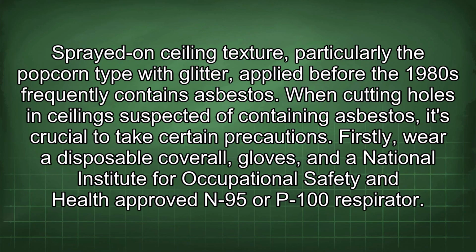Sprayed-on ceiling texture, particularly the popcorn type with glitter applied before the 1980s, frequently contains asbestos. When cutting holes in ceilings suspected of containing asbestos, it's crucial to take certain precautions. Firstly, wear disposable coveralls, gloves, and a National Institute for Occupational Safety and Health approved N-95 or P-100 respirator.